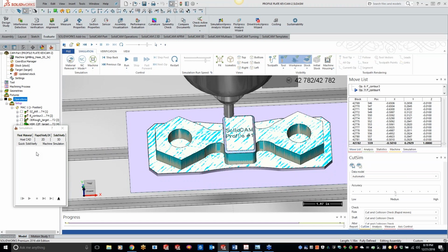It all depends on your machine size and what it can hold for engraving. Yeah, memory limitations could be a problem depending on memory size. That comes up a lot. So Chris, what I would recommend is using DNC and drip feeding it into your machine. That way you don't have to worry about any memory at all. Using the OBD, what is that? Not the OBD2 port, that's in a vehicle. RS-232. Yeah, there you go, RS-232. Using that port, you can drip feed it in there.